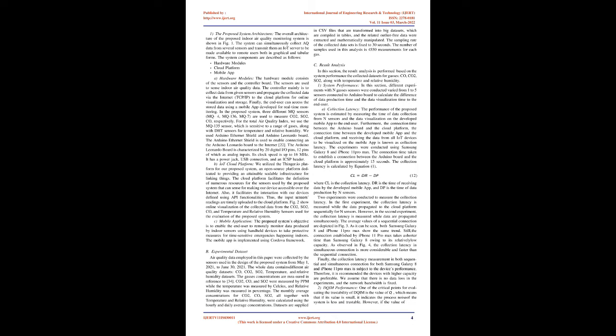In equation 3, the value of Zt, whose accuracy is unknown, is a linear combination of the signal value xt and the measurement noise Vt. In the proposed model, the statistical characteristics of Vt are assumed to be normally distributed with a mean of 0 and a covariance matrix Rt, as given by equation. To obtain the system's optimal state estimate at time t, a linear combination of the system's optimal estimated state at time t-1 and the observation of the system state at time t is used.